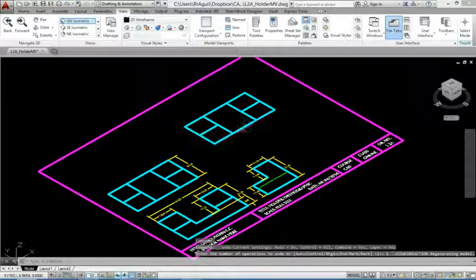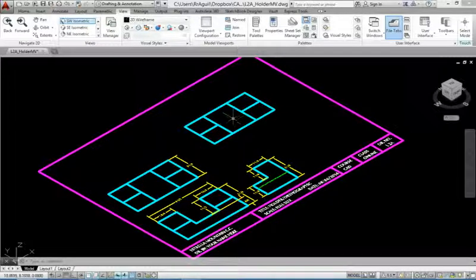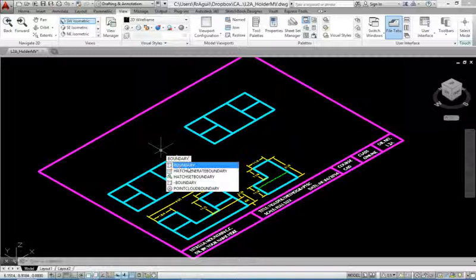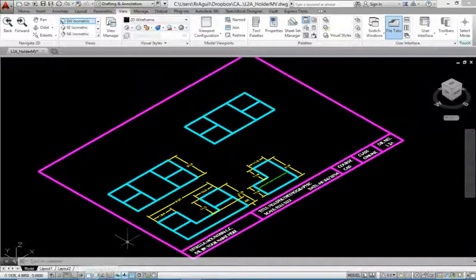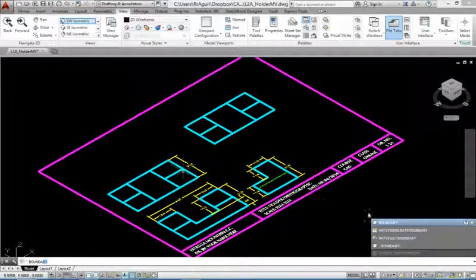I'm going to extrude the boxes that make this 3-dimensional shape. The command I'm going to use is called boundary. If these messages don't pop up on your mouse, below you need to activate this command here, dynamic input. If it's off, and I type in boundary, I don't get any information on my mouse. It'll show up somewhere else, as you see here. Dynamic input is much easier, so make sure that's on.